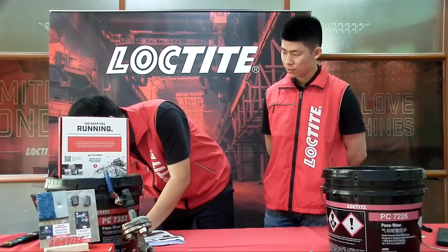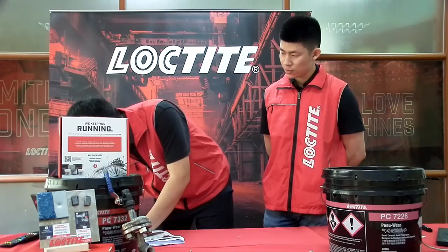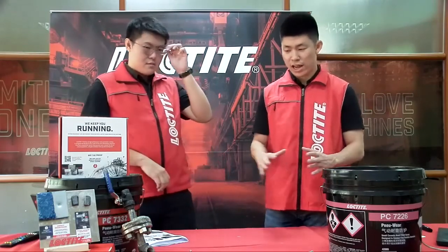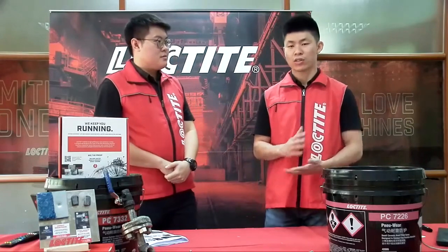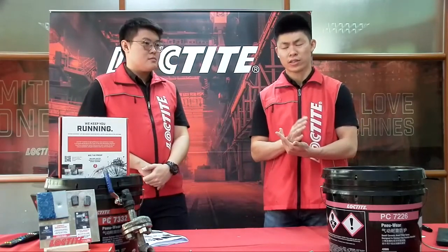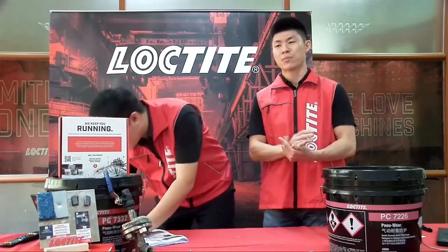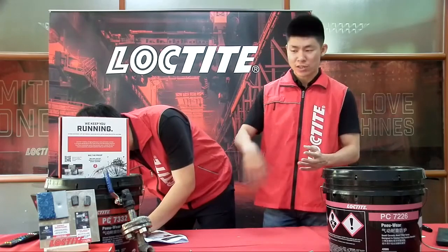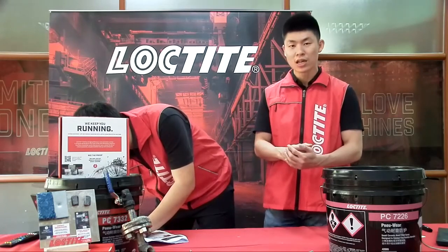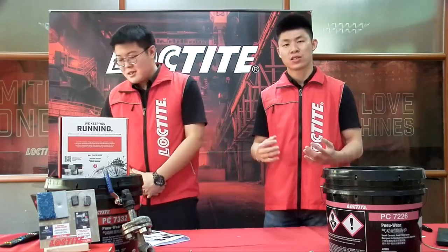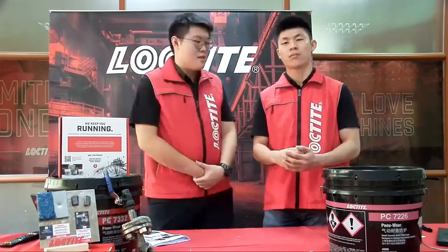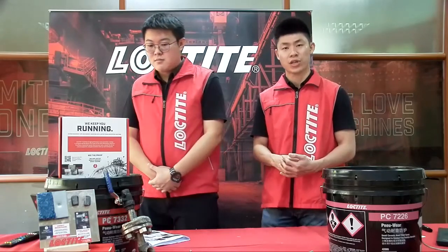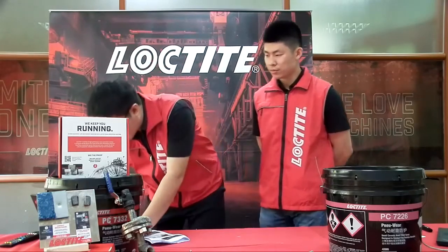There are actually a few audience members asking this: what's the working temperature of all these protection coatings? For all the products that we introduced and focused on today, the application temperature will be around 120 degrees plus or minus. But if you are looking at an application temperature much higher than 120 degrees, then we can use Loctite PC 7338, this ultra high temperature product, which is able to resist temperatures up to 280 degrees.